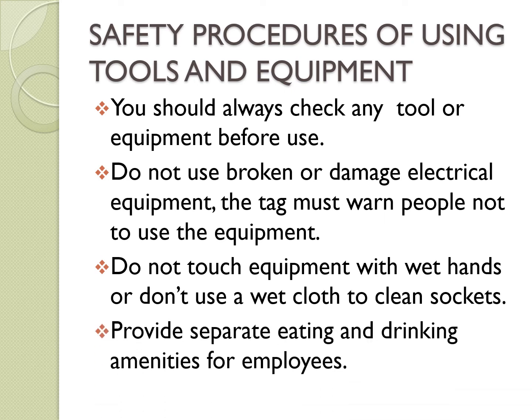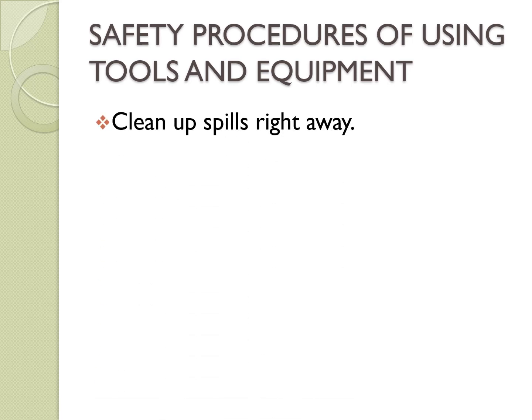Provide separate eating and drinking amenities for employees. Because, as I've said earlier, they are using hazardous material. They should eat separately to avoid sickness. Another, clean up spills right away. Use mats on slippery floor.